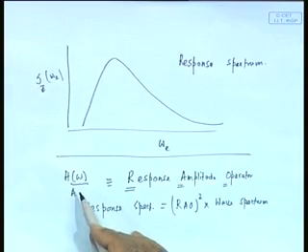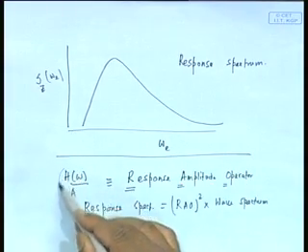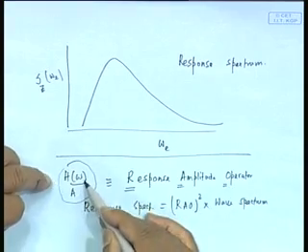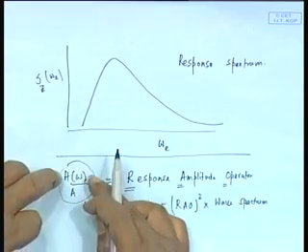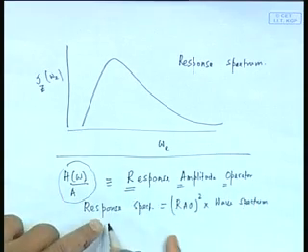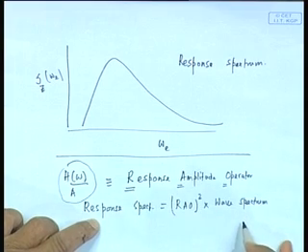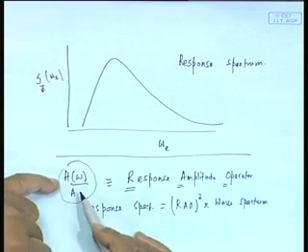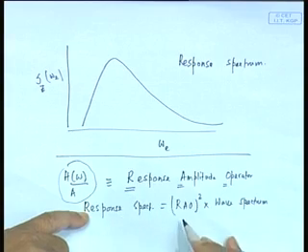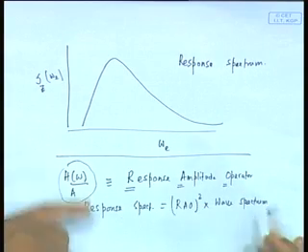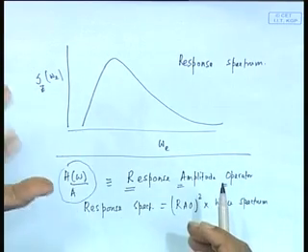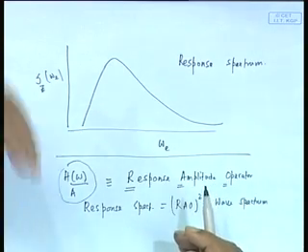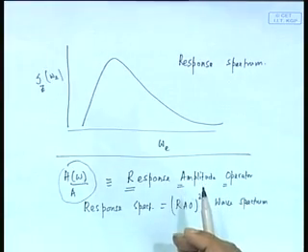So, the response by the amplitude? Yeah, this part. Now, some books refer to the square of that as RAO, so that response spectrum becomes RAO into wave spectrum, whereas some other books will call this as RAO itself, so that response spectrum is RAO square into wave spectrum. So, in the definition of RAO there is some ambiguity: what I call RAO by person X, another person may call the square of that as RAO.